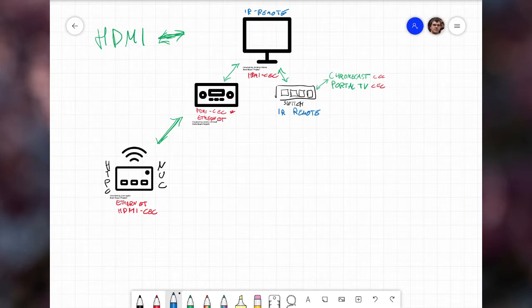As I was saying, the TV doesn't have serial control. Many TVs, particularly those that are often used for displays, for signs, for dashboards in offices, will have a serial-based control, so you can select inputs, change the audio, change the volume, turn it on and off. Essentially with RS-232, some of which are documented. I think the Panasonic panels actually have a documented protocol for that. Some Sony have the serial port, which you're not supposed to have access to, but you can.